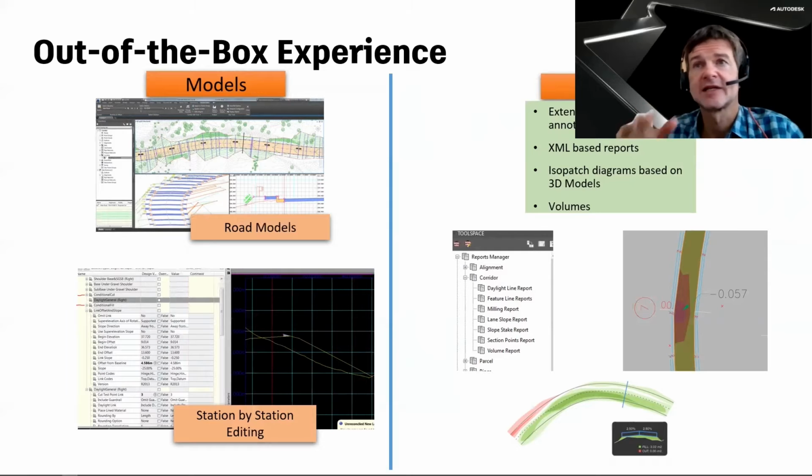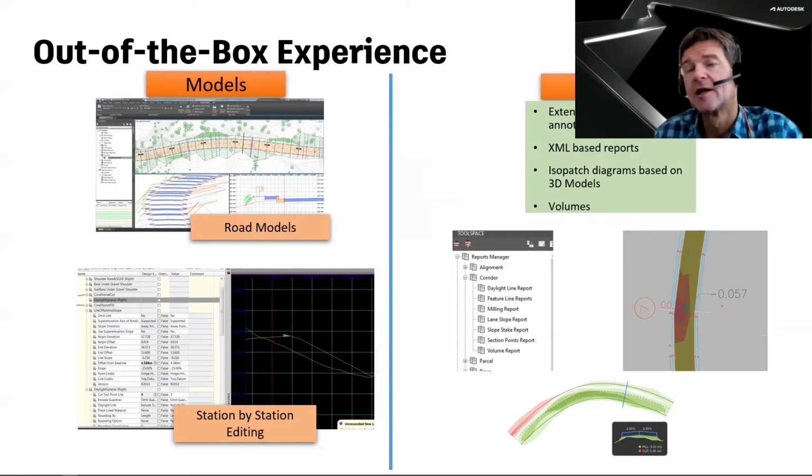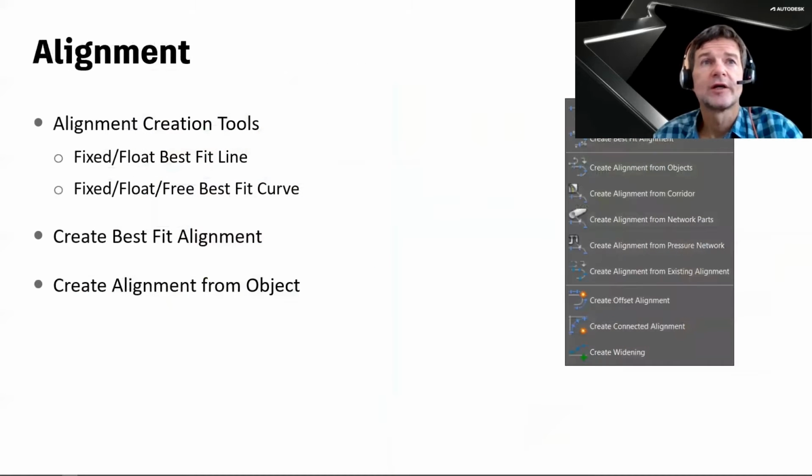You can modify, because as I said, maybe here you have to satisfy some constraints like an entrance to the yard, etc. And then you can do a report, because in reports you will see much better if you are exceeding some crossfalls, slopes, etc. And you can use the standard analysis functionality of Civil 3D, where you will see where is the low point, where is the high point, where maybe the crossfall is not satisfying criteria, and you'll be in trouble with water, etc. So let's have a look at alignment.